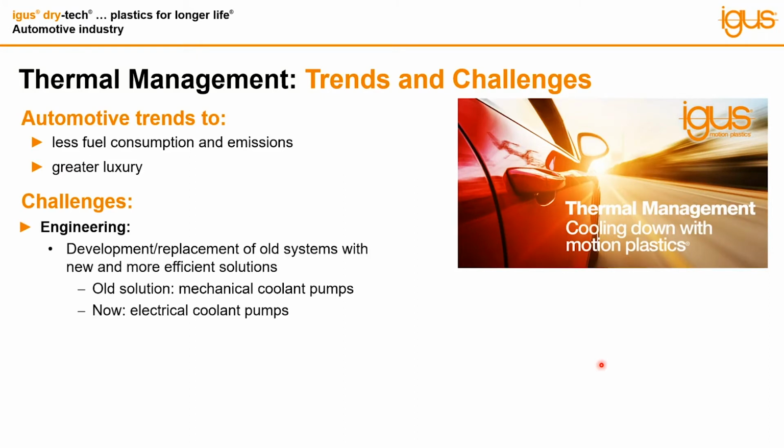For example, we have to check and to develop and replace old systems which are maybe not so efficient in the end, and have to replace them with new solutions. For example, the mechanical coolant pumps, as they were used very traditionally in the vehicles, are nowadays being replaced with smaller and more space-saving and more efficient electrical coolant pumps.